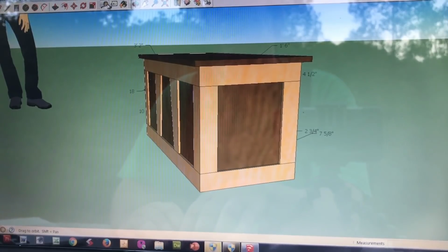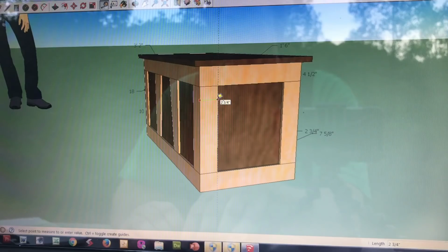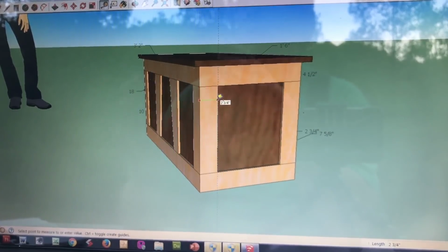When I'm taking my raw material, my lumber that I had milled, that had dried and was ready to go in the workshop, then I knew when I was going to plane it what material we need to start with as far as width and quality goes. So I could start measuring off these things using these tools here and say, okay, I know the stiles and rails that I need to build this toy chest need to be 2 and 3/4 inches wide. So that's when I would start putting my material list together. I knew that's what I needed to get.